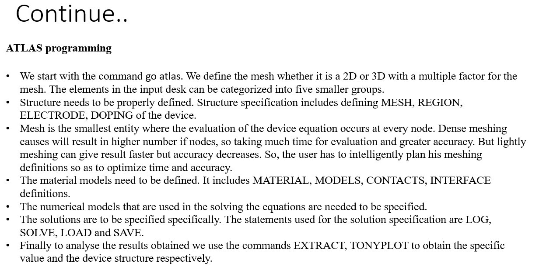The numerical models used in solving the equations are very helpful and need to be specified. The statements used for the solution specifics are log, solve, load, and save. Finally, you can extract the results in TonyPlot and visualize them.